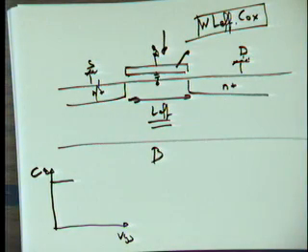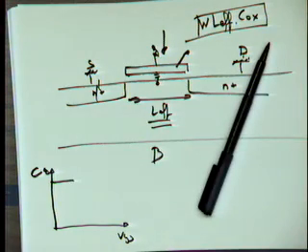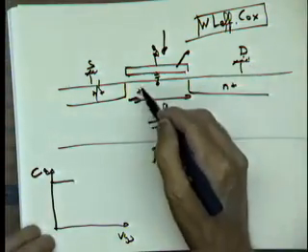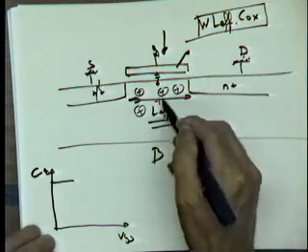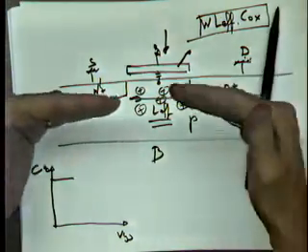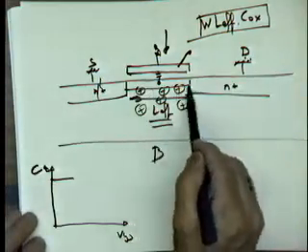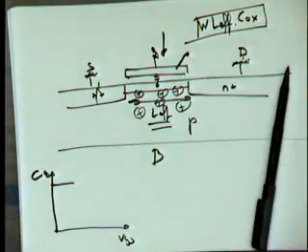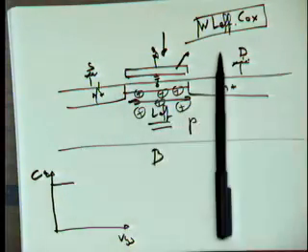Now, remember what's happening when I start increasing the gate voltage. What's happening underneath that gate oxide? What's happening at the surface here? I'm starting to push away holes, right? This is a P material, so I have some free running holes in this. I start to push them away. I create a depletion region underneath the gate. Now, if you remember something about diodes, you know depletion regions have capacitance connected to them. It's like a capacitor.